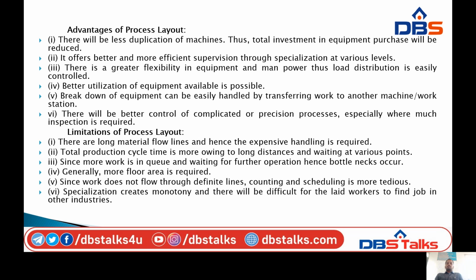The advantages of process layout: there will be less duplication of machines. Thus, the total investment in equipment purchase will be reduced. For lathe operation, one or two lathe machines are enough. But in product layout, we have to provide a number of lathe machines, and a number of drilling and milling machines, so as to maintain the operations in a sequence. There is no replacement or transportation or position changing of the equipment in process layout.